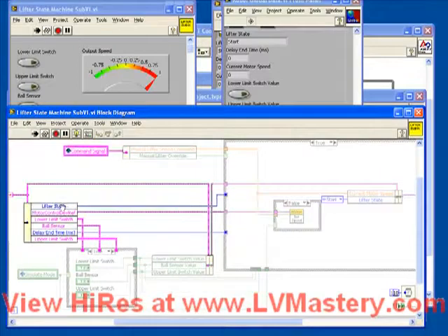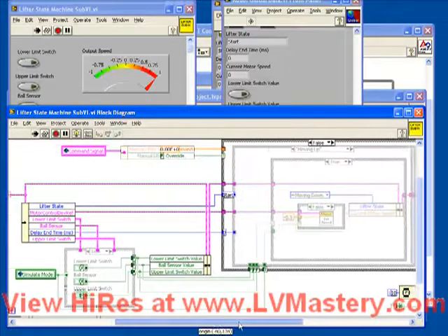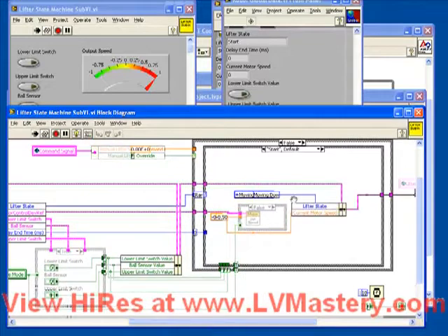We see that our initial state is start, as we expected. Our command signal is 0 and false, which is good. Our simulate mode is true. Our three booleans are false. So we immediately go into the start case. Our output speed has been set to -0.5, and our new state is moving down.